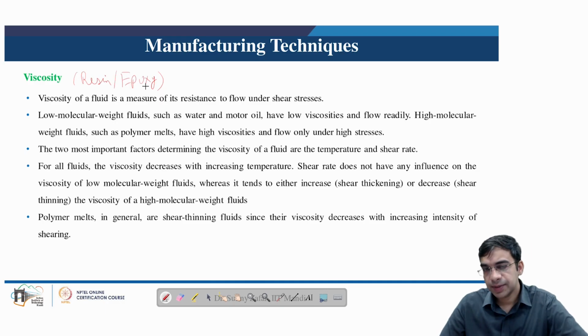The epoxy, especially when mixed with hardener, has high molecular weight, and such polymers melt at high viscosities and flow only under high stresses. Because of this high viscosity, appropriate pressure needs to be applied so that the viscous epoxy can flow in the complete mold and thereby completely wet out the fiber which is pre-placed.